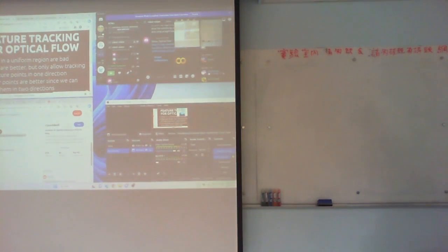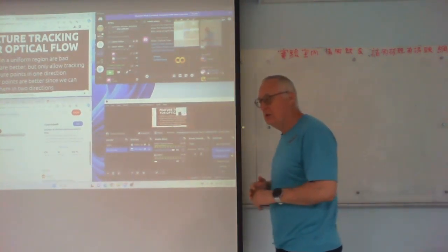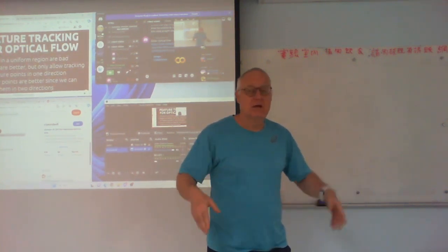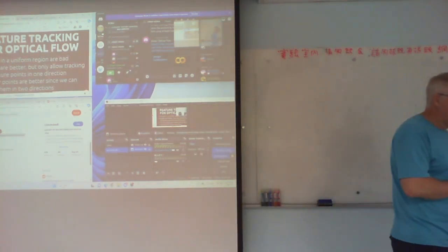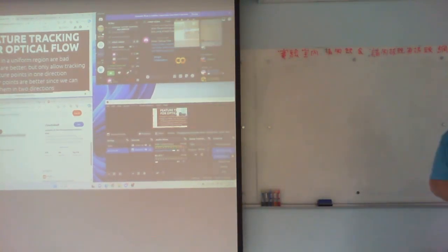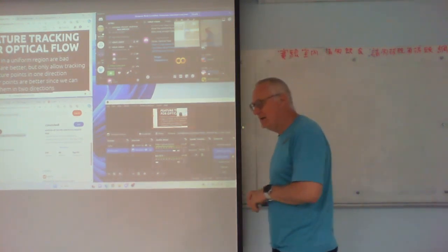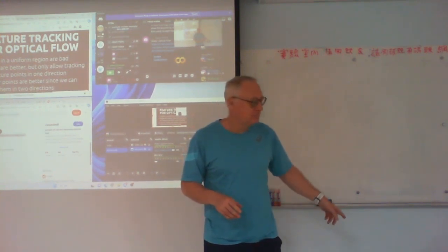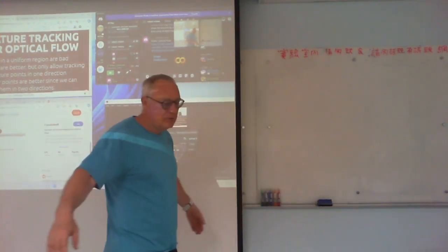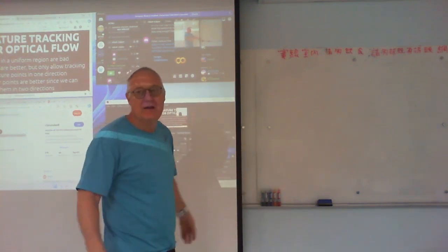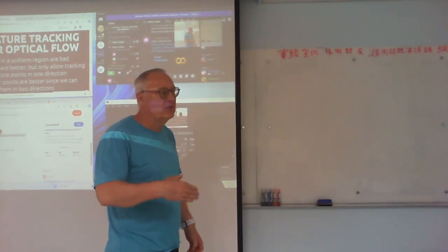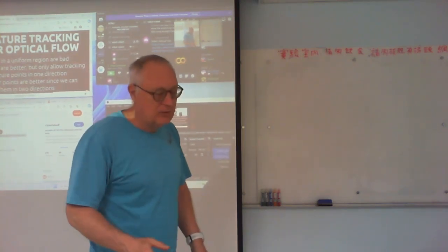And that's actually enough in the soccer domain. We implemented quite good localization algorithms just using the field lines. If you can detect those well enough, then you can track your position. But that's also okay in the soccer domain, right? Because there we were mostly interested in the sidelines, because the sidelines tell you the direction and how far away you are.